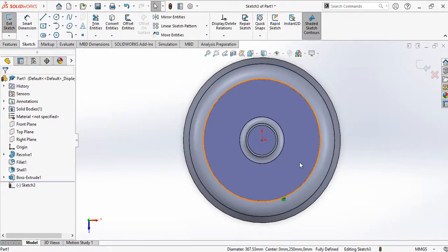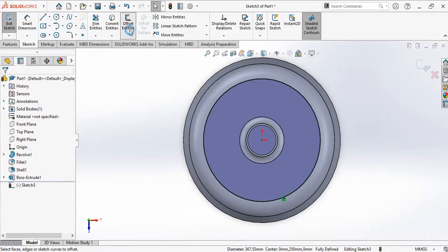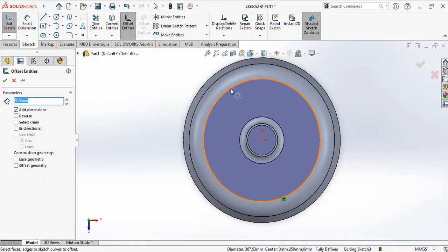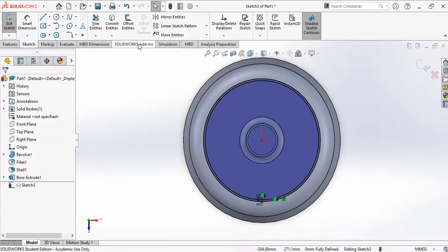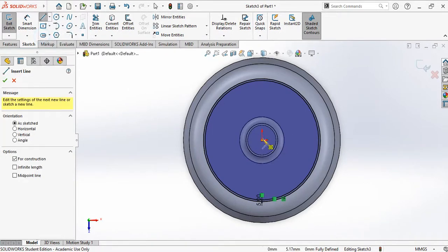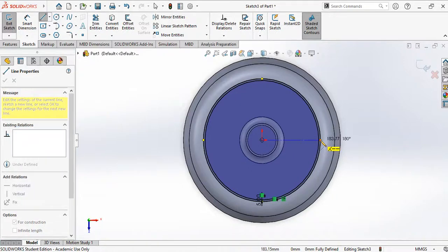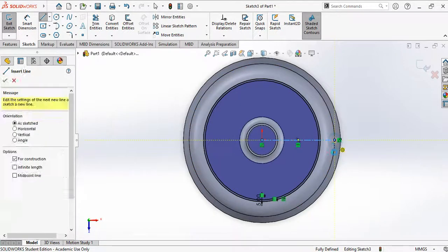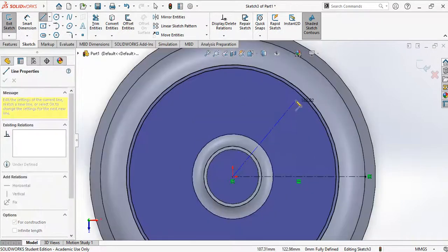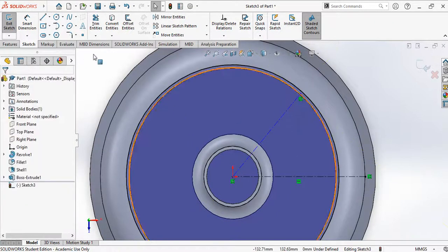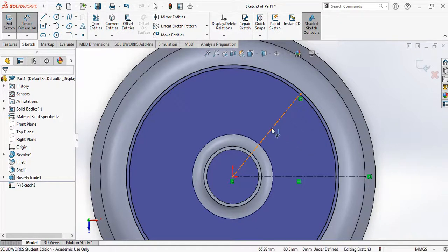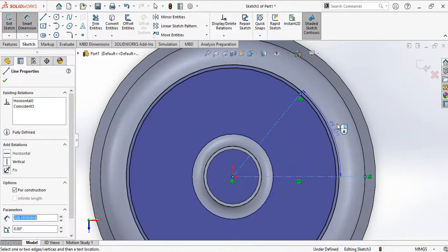You see it gives you a circle, and we use offset 5 mm. Click on this line, make sure it goes inward, confirm, and we need an opening of 50 degrees. So usually I will prefer to use this center line. I will use this center line, then I will use this as center line. I will sketch somewhere here, and I will put here a 50 degree.